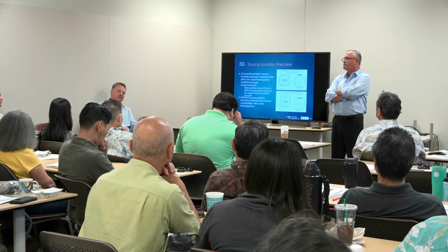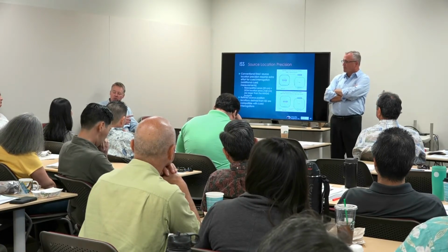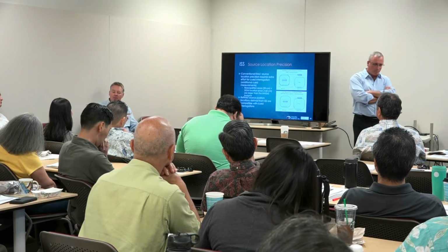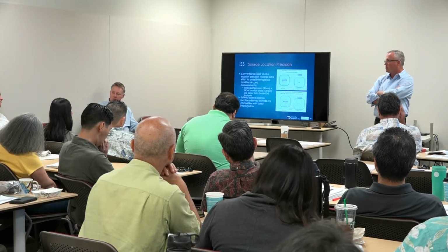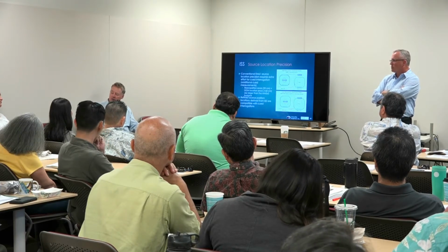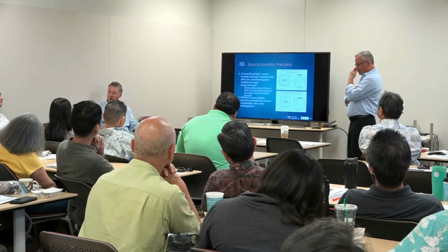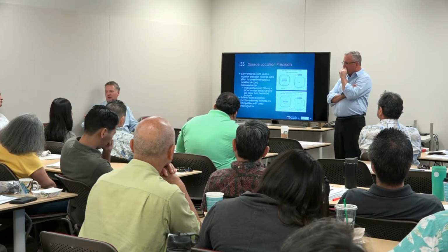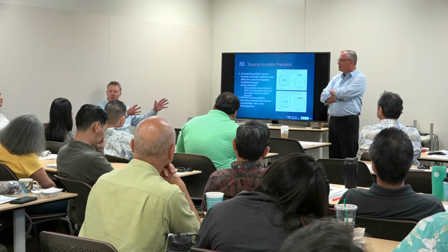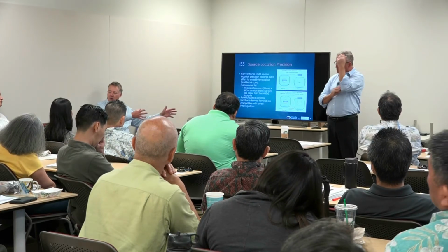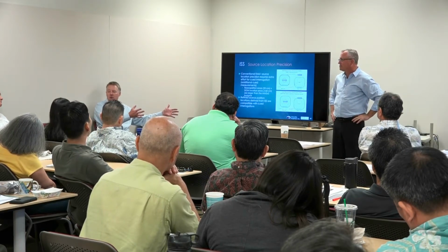I'm going to actually flip it on its head, and at the end, when I'm talking about regulatory considerations: from the regulatory perspective and the safety perspective, I'm much more concerned about the don't dig decisions and how to QC and how to verify the don't digs, because those are the things being left in the ground. Once they decide to dig it up, as long as we make sure that they dug up the object that they were going after, that's good.